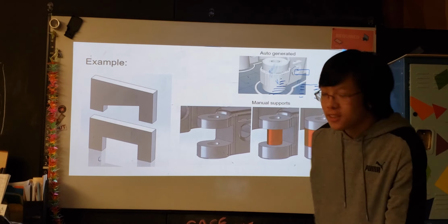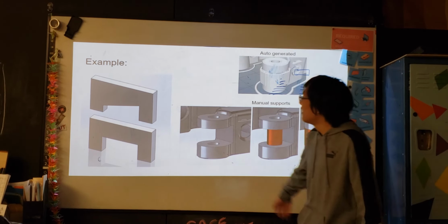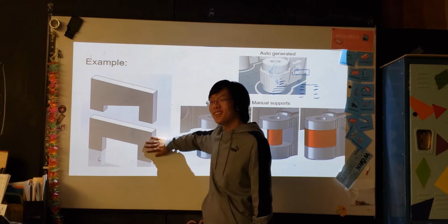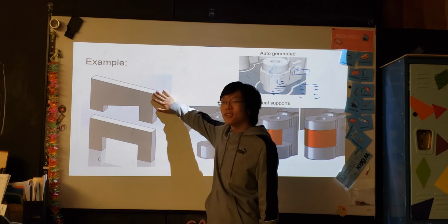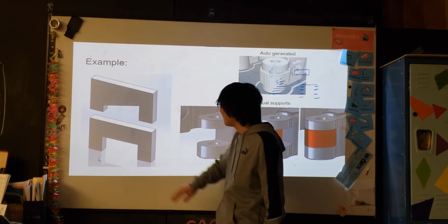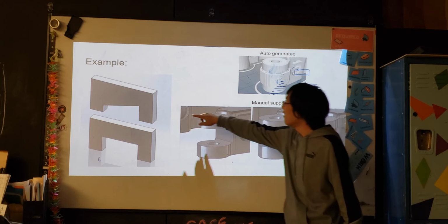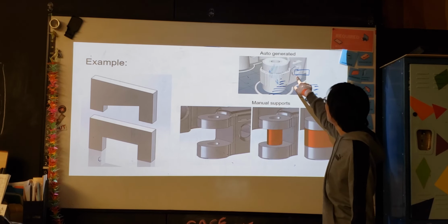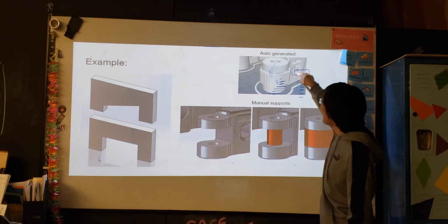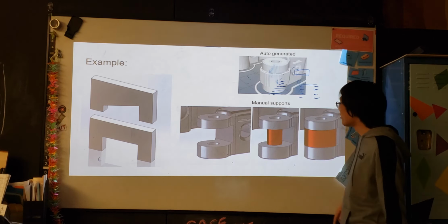All right, so let's quick recap. Which one's better to print, this or this? Bottom. The bottom. Yeah, because what it's doing here is making a bunch of these where the edge isn't supported by anything. It'll turn in midair, and that will suck.